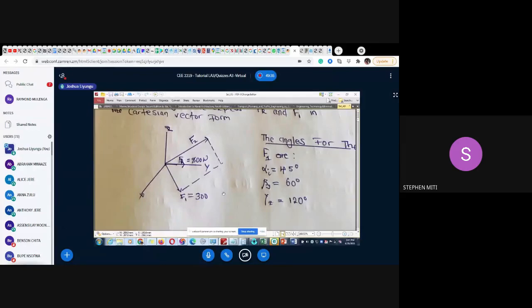So now we are going to add the components of F1. And the F2 will be just in terms of components, since we are not given the magnitudes. So we are going to say F2x i, F2y j, and F2z k. The resultant force has only the component along the y-axis, which is 800j. So we can find F2y, F2x, and F2z from there, and its magnitude using the formula. Okay, sure, I'm done.